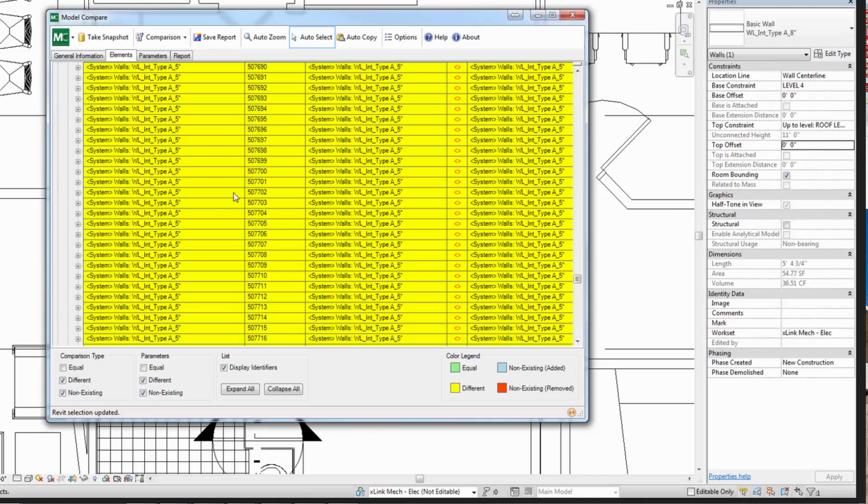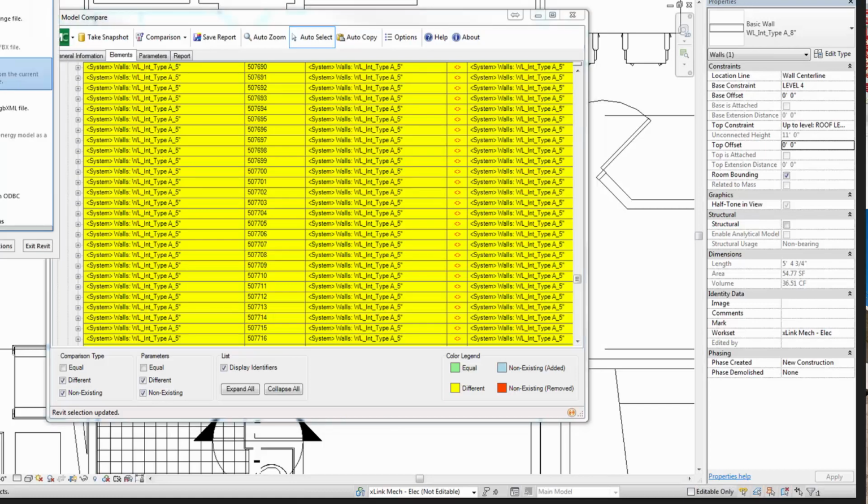It's data that we're going after for the ability to compare, but we don't get everything. There's certain things the API doesn't give us access to, and because it doesn't give us access to it, we can't actually do anything about that. We can't actually create information we don't have. Whereas if you were to go through something like the application menu here and export your model out as a GBXML file, or even an IFC, IFC actually stores information about a project and it can recreate it. But even that loses some fidelity when you go out of one file format to another because you just can't keep all that information. So unfortunately, no, this does not actually recreate.